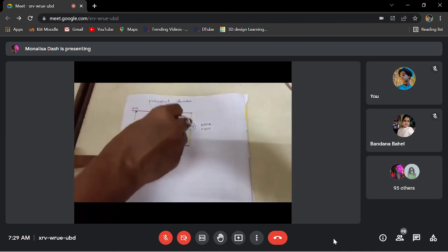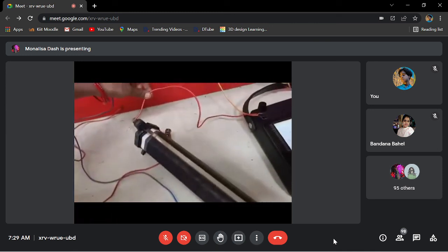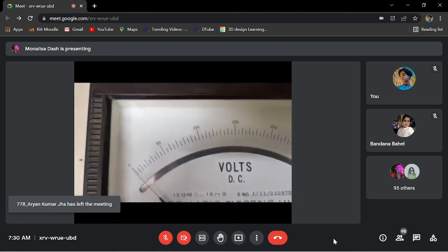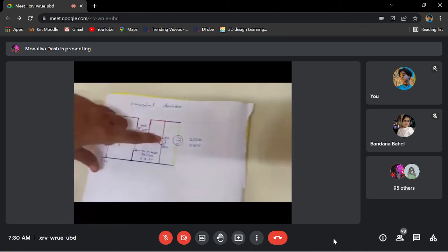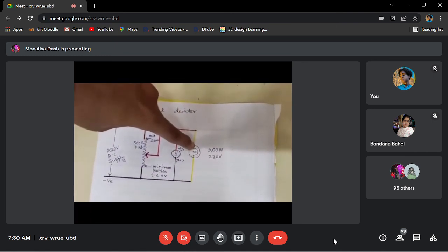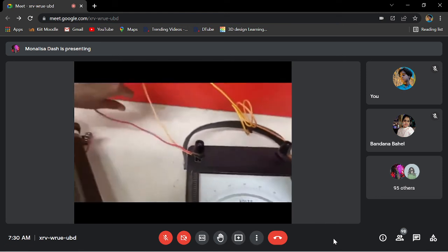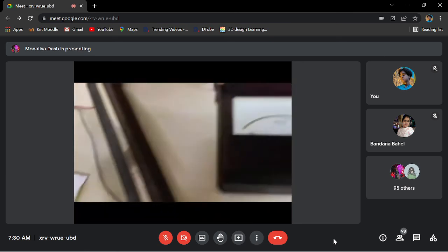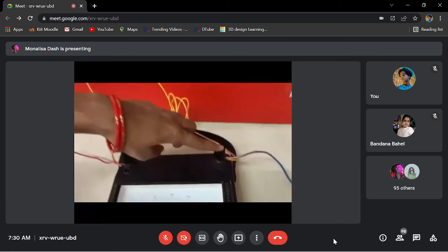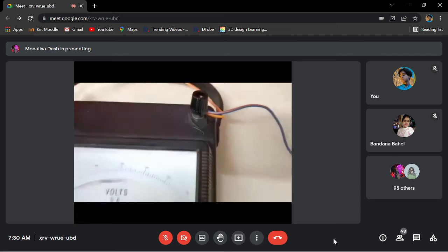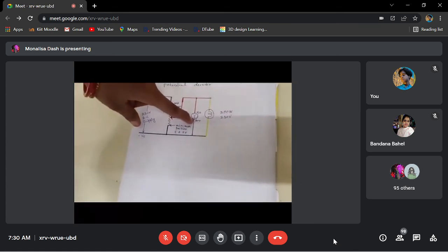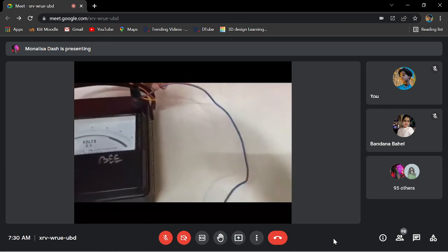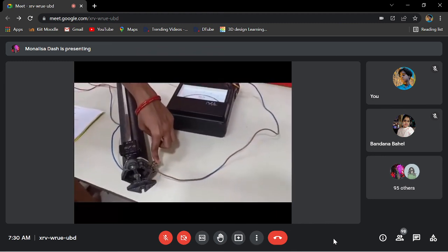The variable point goes to the common plus point of the voltmeter, and from the voltmeter it goes to the bulb. The other end of the bulb goes to the voltmeter 300 point, and from that 300 point it goes to the fixed end of the rheostat.